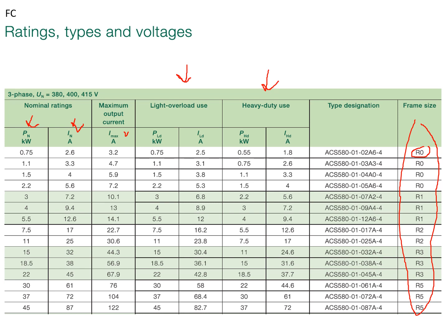This is the same frequency converter, this line, but if we use it with a light overload application like a pump, for example, or fan, those applications do not include any overloads at all. Then we can run this particular inverter in this line with the motor which has 0.75 kilowatt power.